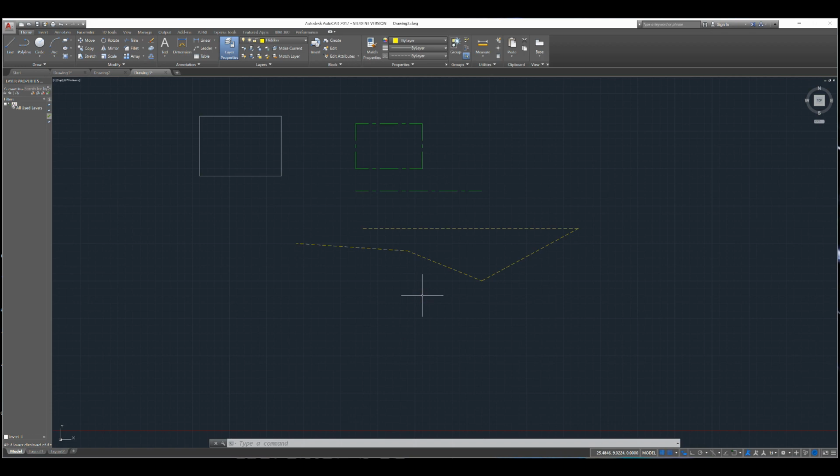There's one other thing that you can actually do, and it is called, if you type in LTS, it's your line type scale. It's set to 1 as default, but watch what happens when I change it to 4. My lines actually get more space. So it literally scales the size. It was default 1, I changed it to 4. You notice how the lines got bigger and the spacing got bigger.